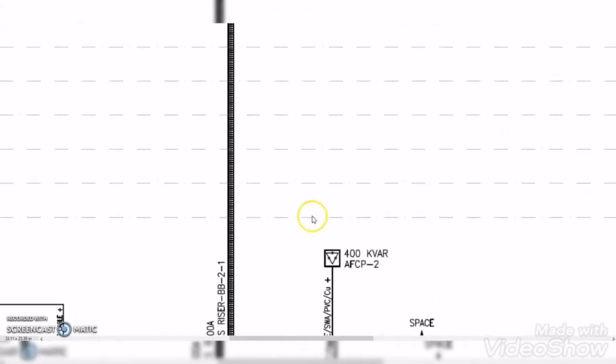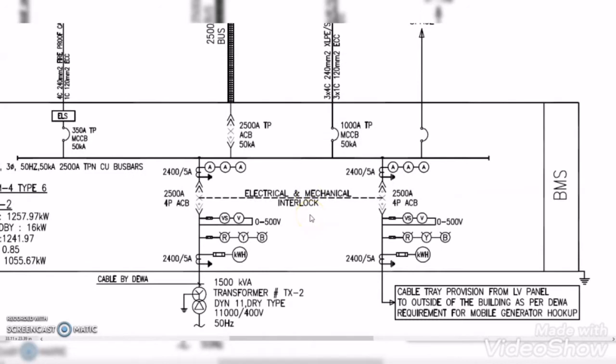If we refer to the final distribution board breaker short circuit capacity, which is fed from these SMDBs, we will find that it could be 20 kiloamperes or 25 kiloamperes, because the prospective short circuit fault current at the final distribution board level is a maximum of 20 to 25 kiloamperes. So it is very important to find the prospective short circuit fault current at each